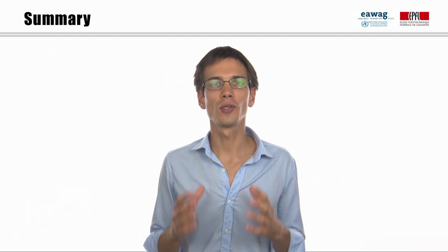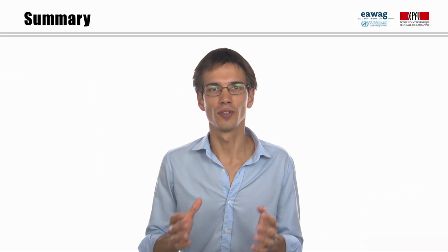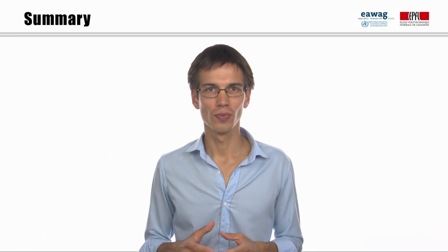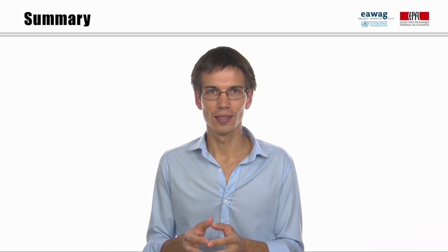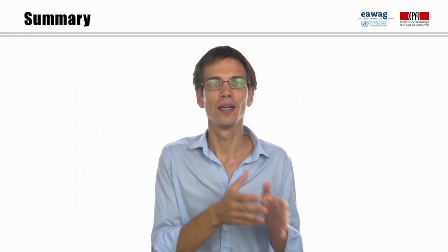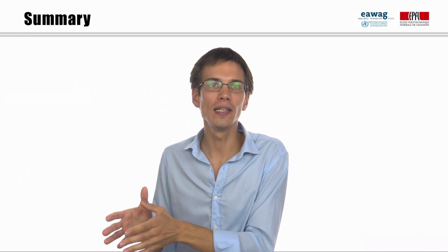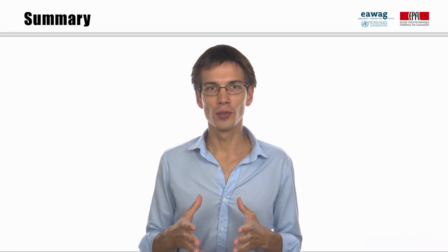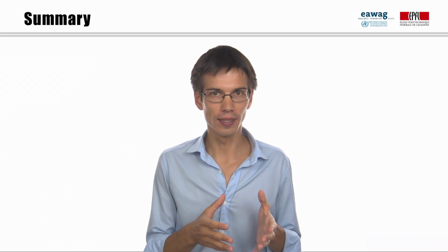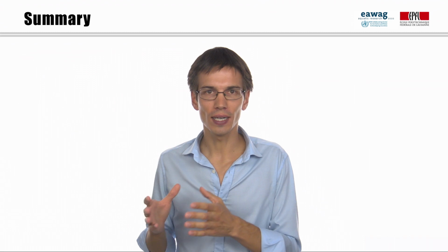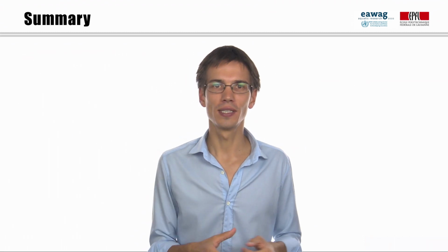To sum up, we saw that treatment is a succession of different steps, the main ones being the primary and secondary treatment. Pre-treatment is a must as a kind of preventive measure, either at the household level, at the street level, or at the inlet of a treatment plant. Post-treatment is not always necessary and a pragmatic approach is recommended. The effluent quality should match the intended end-use practice or the quality of the receiving water body.